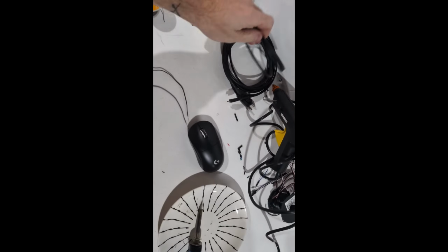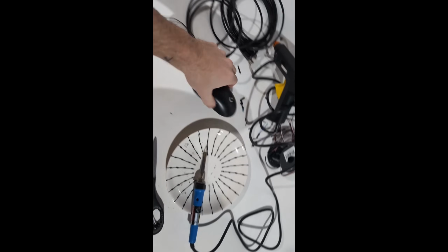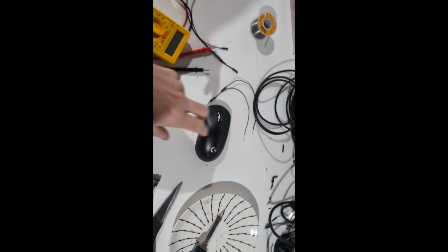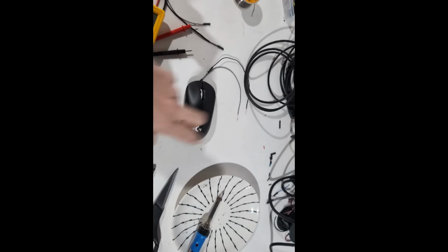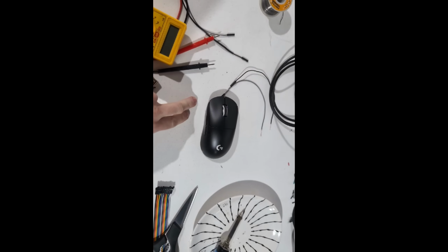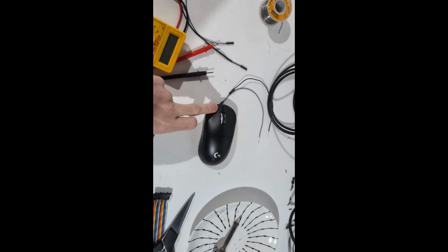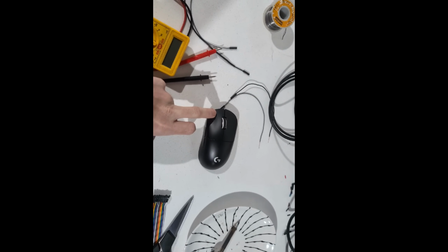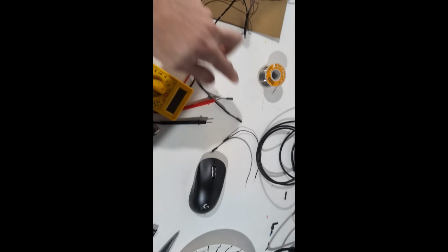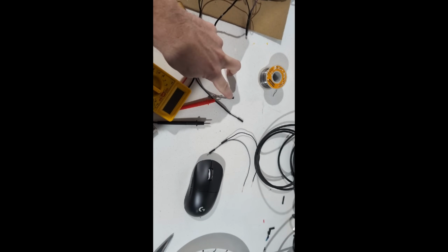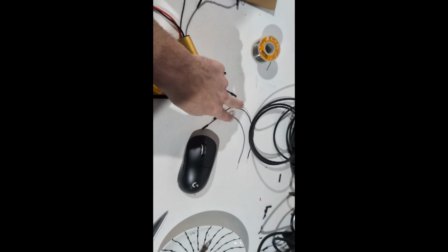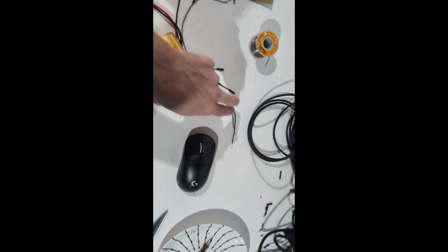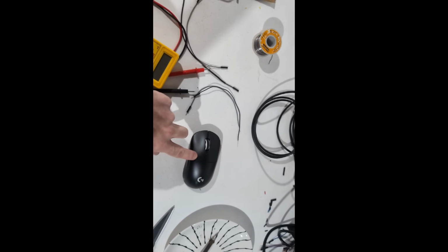We're going to have to get our mouse cable. We're going to have to get our mouse. We're going to have to take apart the mouse, plug it into the PC, and find out which one is earth and which one is the 3.3 line. The earth is going to need to go to black, and the 3.3 line is going to need to go to the grey. And we're actually going to have to solder these onto the switch itself. So it's going to be quite tricky, this one.